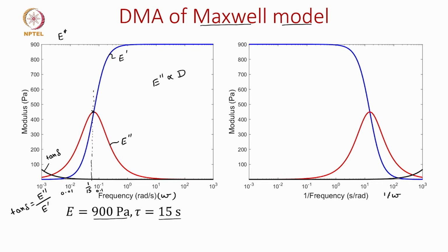If we are talking about low frequency, let us say this is a specimen and we are doing this axial test in a cyclic fashion. If I say that the frequency is small, it means the loading is happening very slowly. In contrast, if the loading frequency is high, the strain rates or stress rates it will see are higher, which means this also indicates time in this expression.